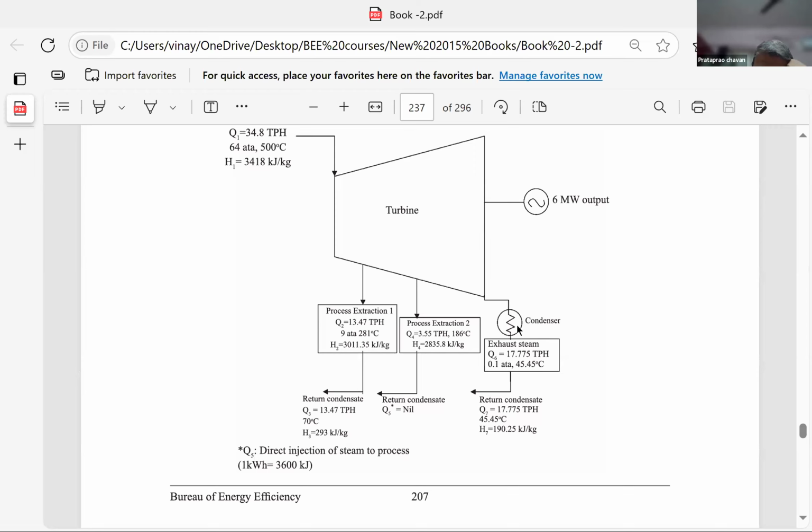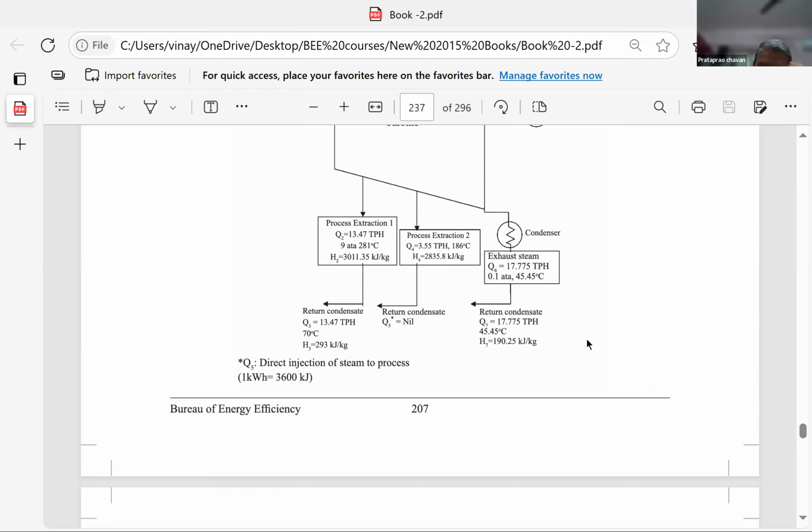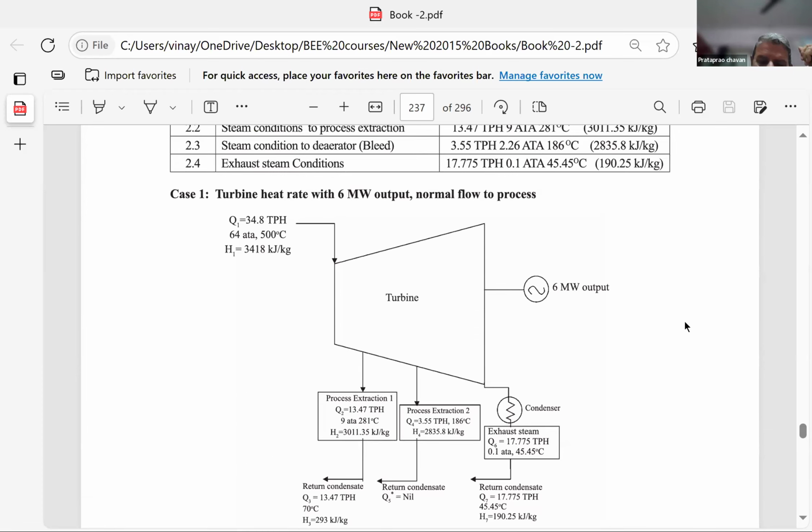And the third heat goes to the exhaust. There all things are given. Flows are given in kg or tons. The total heat content per kg is given. And here you can put a small heat balance. This is the heat input. This is the useful electrical output. Now this electrical output you can convert into heat units, or these are three sources where the heat is diverted.